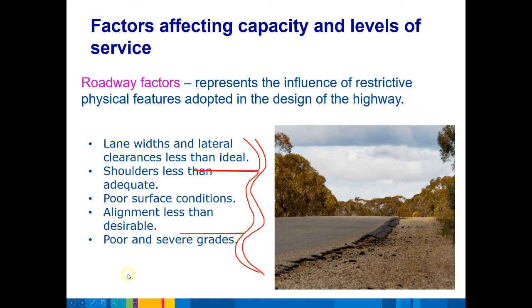There are lots of parts on the Western Highway where if you're coming from Melbourne, you're climbing up a hill consistently at 6% for kilometers, because you need to climb. 6% over a kilometer distance only gets you 60 meters, and Ballarat is at an elevation of 400 meters. So there are some sections there where you've got to climb up quite a bit.